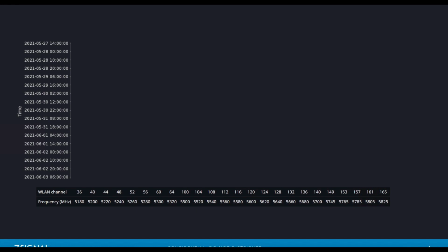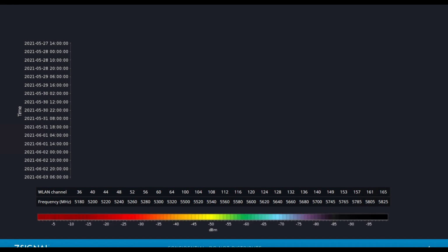And then the third dimension on our graph is the magnitude, how loud, and we measure that in, as you know, the dBm. And this is the sweet spot right here. So we all talk about, well, what is a good signal strength? It's got to be right around this -65 area that I'm pointing to on the graph. And just pay close attention to the color. Okay, it's kind of this really nice aquamarine turquoise.